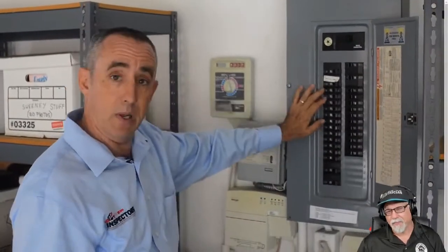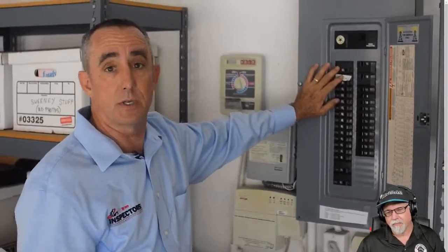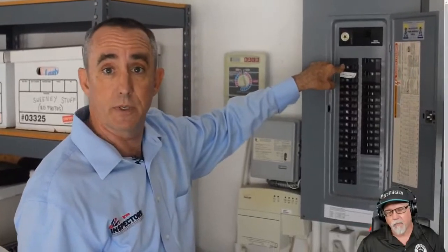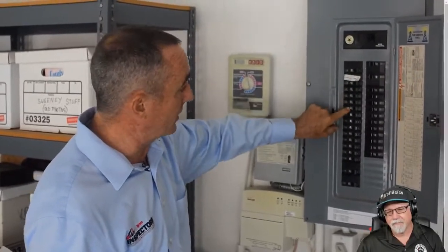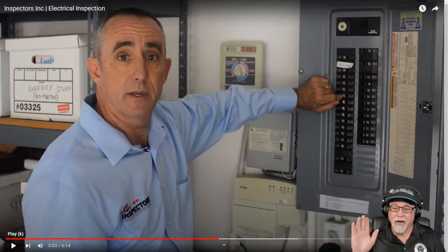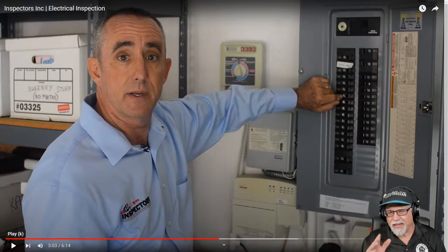However, if you have one appliance, for instance, the stove is malfunctioning and it's using up too much electricity, instead of it causing a fire, it'll trip the breaker individually. You'll notice that they'll have a little red spot on them in the window glass. Remember now, not all breakers have that sight glass. That's very unique to Square D. Schneider, Cutler Hammer might not have it. Siemens might not have it.